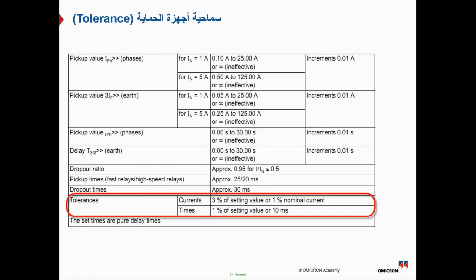If you are testing manually or using the general test modules, you have to define which one is used to assess the test results. Normally, if we are using the automatic testing approach or our PTL, it will take whichever is greater for the relay assessment of the protection results.